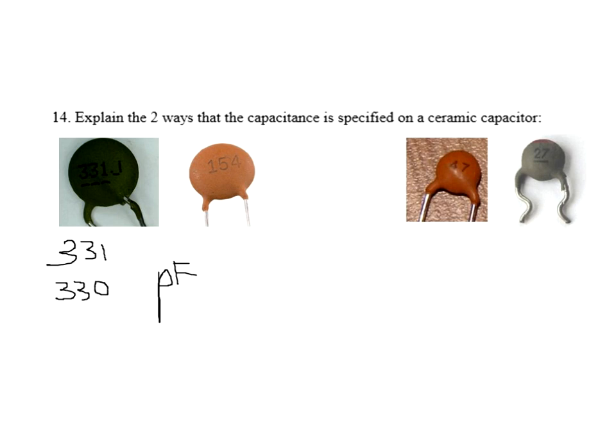If you need to change it to microfarad, you move the decimal places 6 places to the left. But first you should go to nanofarad. So this would be 0.33 nanofarads. And I would move it 3 more places for microfarads. Micros times 10 to the negative 6. And what would that be? Let's see, that would be 0.00033 for microfarads.